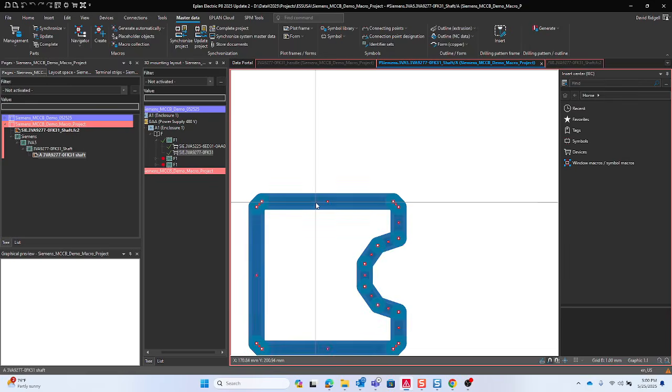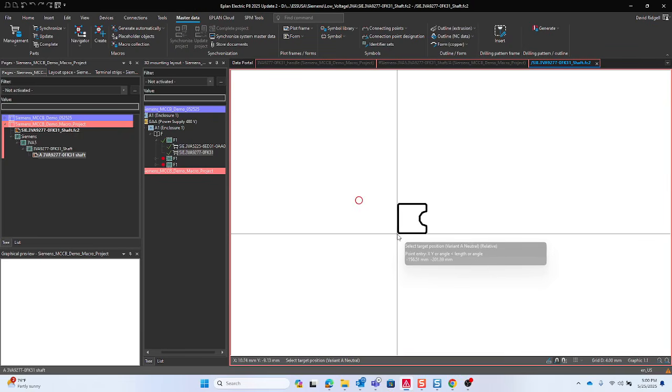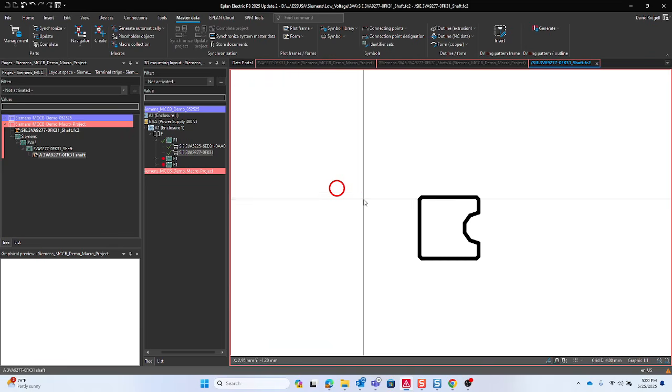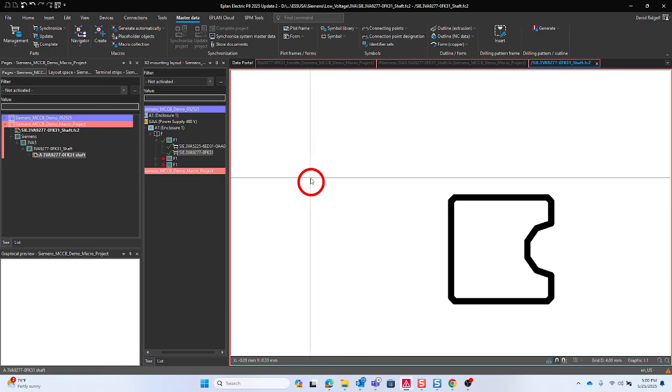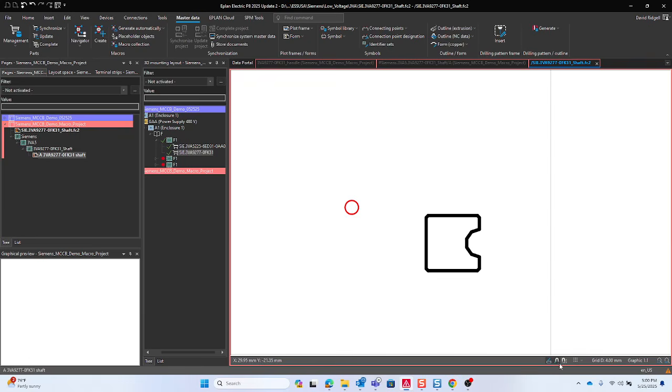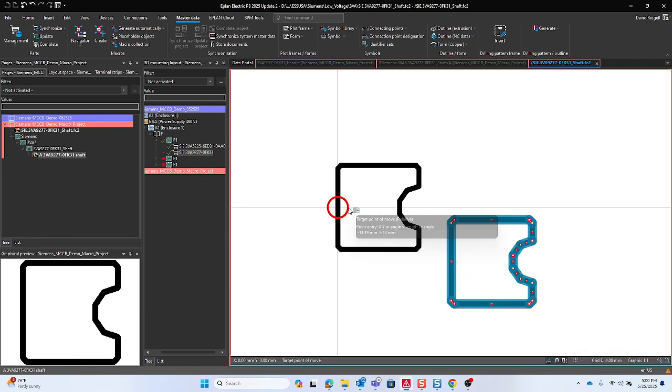We'll go over here and we'll copy this polyline here, paste it in here, and then I want to kind of center up the middle with the 0, 0 point here. So we're going to turn design mode on and the grid snap on. Highlight that. Object snap needs to be on as well. Take that point and then place it right there.